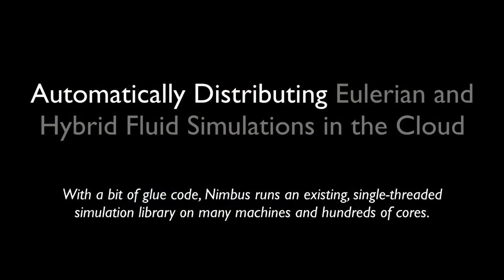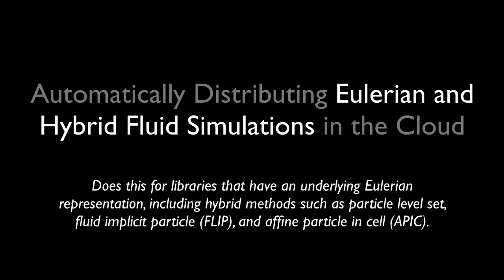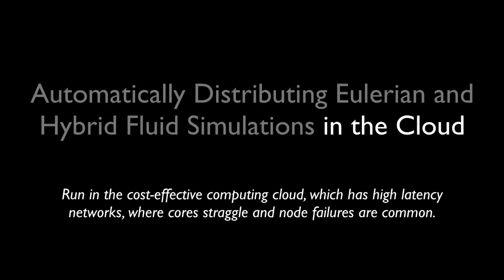So I'm going to talk about a software system called Nimbus, which allows you, with a little bit of glue code, to take your existing single-threaded fluid simulation and scale it out to run on many machines and hundreds of cores. You can do this for simulations of an underlying Eulerian representation, including particle level set, FLIP, and APIC, but you can't really do it for something that's purely Lagrangian, or cloth. And it does this on cloud-based nodes, where you can have performance variations, cross-traffic in your network switching fabric, node failures, and all the kinds of nitty-gritty systems complexities that occur, and it handles all that for you.